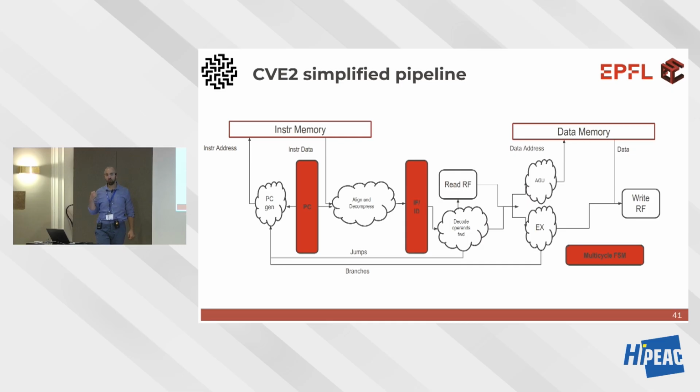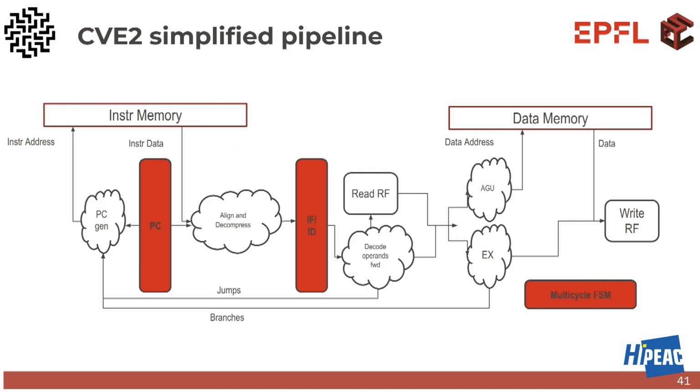What I didn't say before is, or maybe I did and I forgot, it's 2 pipeline stages, very, very small. So you remember the goal was low area, okay, low area. So I can save on the number of pipeline stages. Pipeline stages means registers.